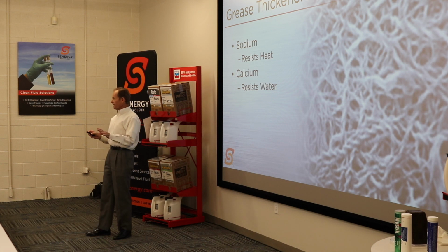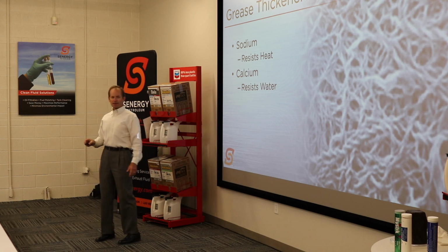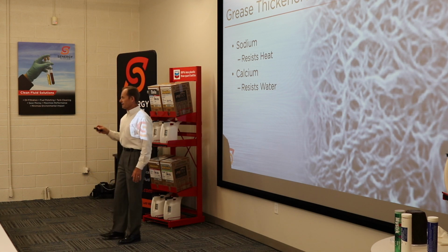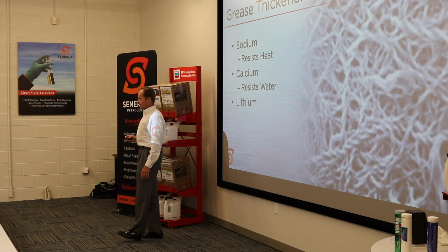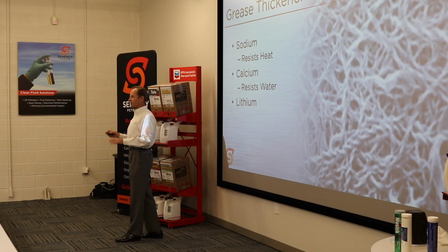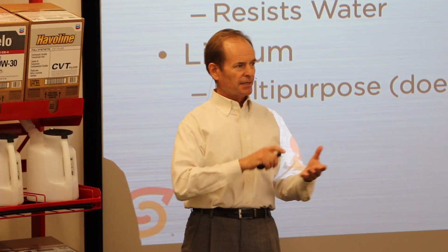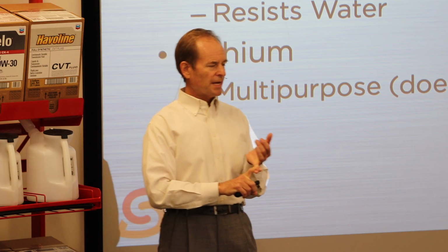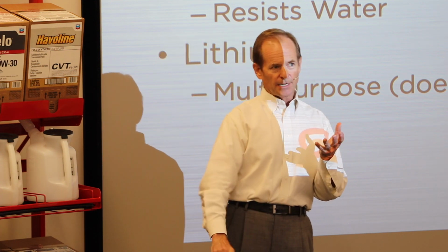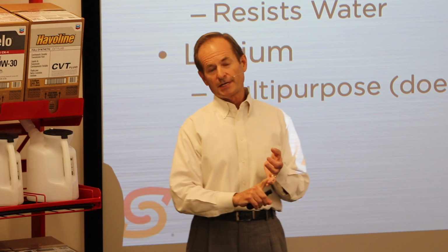So it was quite a revolution in the grease business when they came up with lithium-based greases. This is your standard lithium 12 type grease, still around today. Lithium was considered a multi-purpose grease, because it did both. It handled heat as well as or better than a sodium grease, and it handled water as well as or better than a calcium grease.